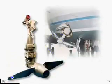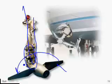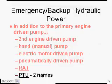Here's a RAT out of an Airbus. I don't remember which model it is, but there's a hydraulic pump in here somewhere. And the air blows across these blades. The blades spin. Hydraulic fluid comes in, gets pumped out at a high pressure. And on a lot of airplanes that are electronically controlled flight controls, digital fly-by-wire, we're also going to use a RAT to drive an electrical generator. So if you had full electrical failure and full hydraulic failure, you'd still be able to operate the primary flight controls at least a little bit.